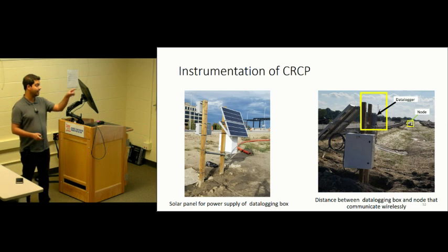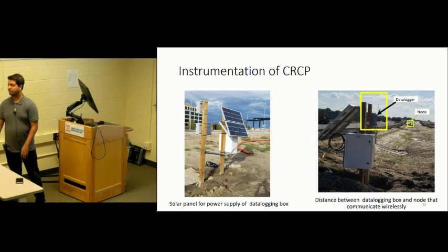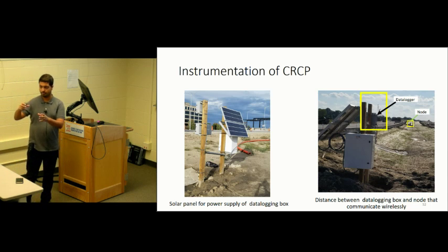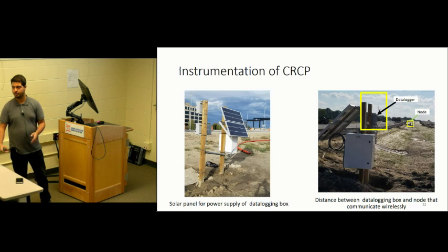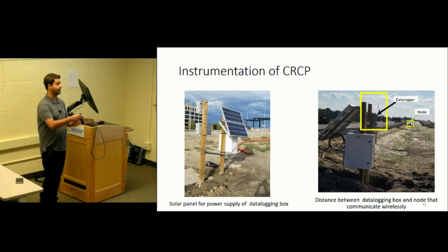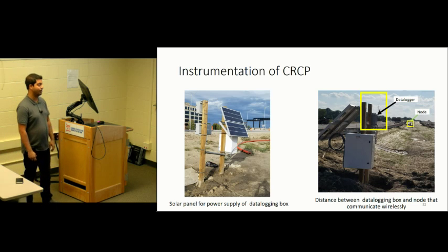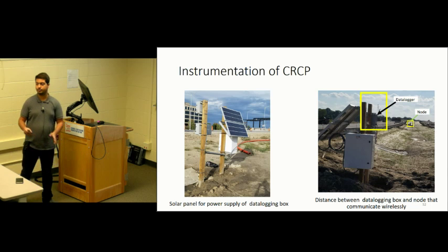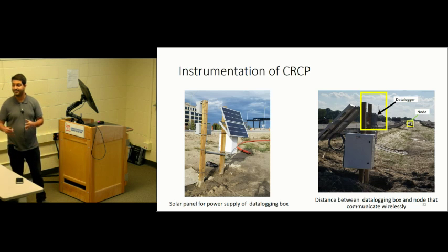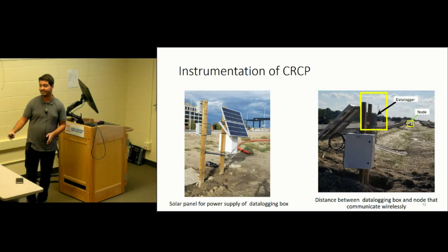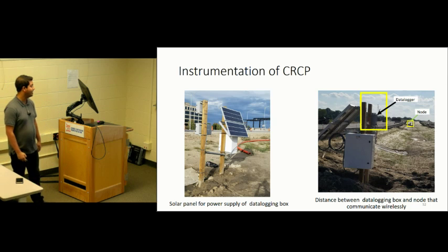Each individual node has around 15 sensors connected from the node box. The wire goes under the shoulder to the concrete pavement, and we don't have to connect any wire from that to the data logger. That saves a lot of wire when we have 2 sections that are 2,000 feet, and each section has around 15 sensors.